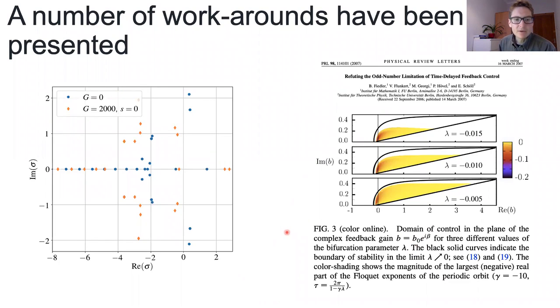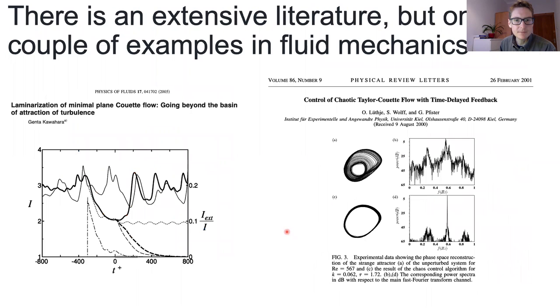But it's obviously something we're going to have to be mindful of in the high dimensional Navier-Stokes case, where at high Reynolds number you're expecting to have very high dimensional unstable manifolds, and the likelihood is you're going to pick up eigenvalues which are purely real. And as I said, this is probably the reason why we haven't seen it used to great effect in fluid mechanics.